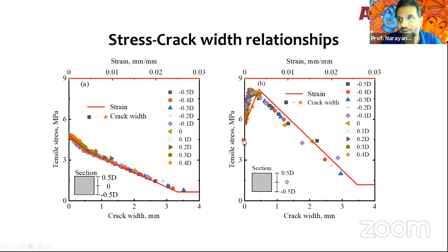And a 2 millimeter crack is a big crack, right? For anybody who looks at a concrete structure, a 2 millimeter wide crack is a really, really big crack. Even with that 2 millimeter crack, look, I have tremendous load carrying capacity, which means your structure can be designed in a much more ductile regime. Your structure can be designed for a lot more ductility than you traditionally use it for. So that is another way of showing it.